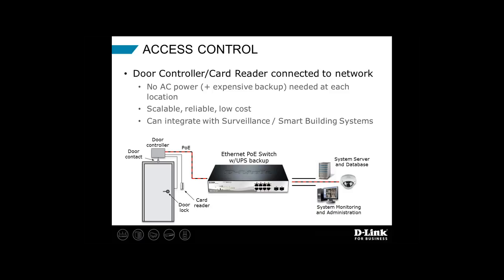Here's one, access control. Quite often you've got door controllers or badge readers or card readers that can be PoE powered, and there's a lot of benefits to doing that. If I don't have PoE powered door controllers, then I've got to get AC power out near that door, and I need probably pretty expensive AC power backup. In the event of a power failure, I still want to be able to operate that door. That can cost a lot of money.